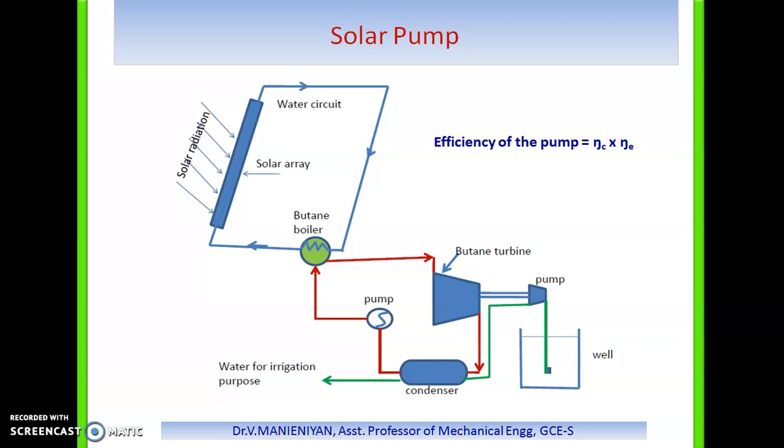It is a low value, but if you increase the efficiency, that means the collector must be improved. The Rankine cycle efficiency will be within acceptable limits if a temperature of 200 to 400 degrees Celsius is provided for the proper functioning of the collectors.